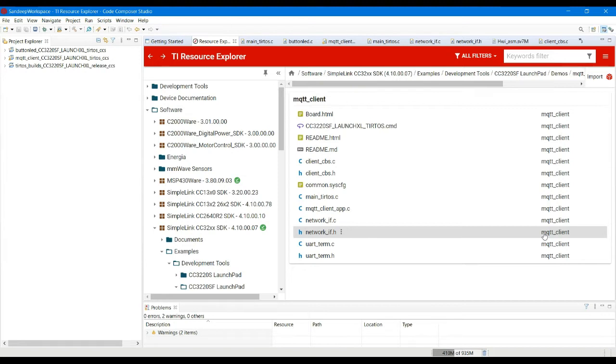Then in a separate video I will give a description of DMA as well as the SPI and I2C, because DMA is something that really works between your peripherals and memory, I mean from memory to your peripheral, or from one memory location to another memory location, or from a peripheral to the memory. So mixing DMA with SPI or I2C or UART would be a good way, or even ADC would be a good way to put your hands on these things.